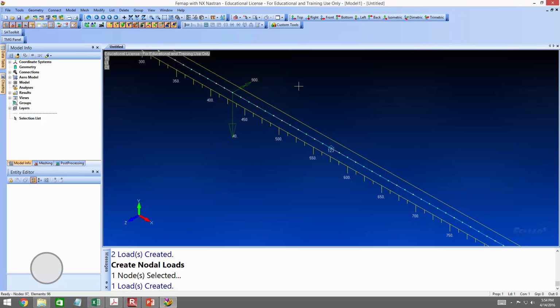All right, did I go too fast? Does anybody need any help? Everybody good? I did not follow the last step. What part? After pointing on the loads. After what? I couldn't hear the last part. The one where we pointed out the Z direction. Well, I just hit OK. After pointing down the loads in 40 kips, after that, this step I did not follow. Well, I just redid it. I did a nodal load at that location. But then over here, I've got to turn it into a moment. And then it's in the Z direction. Yes.